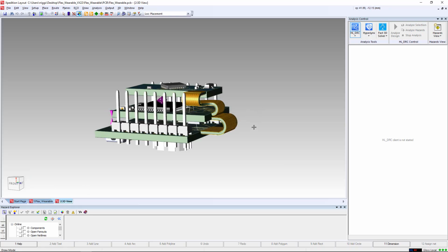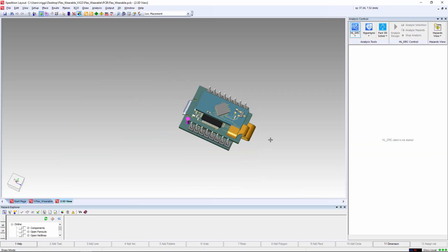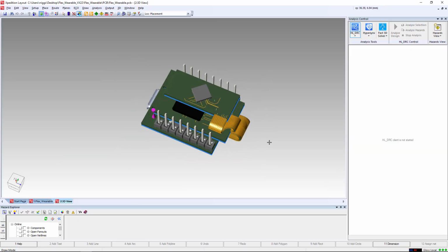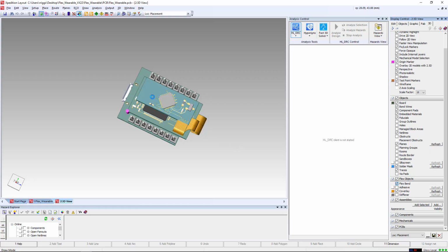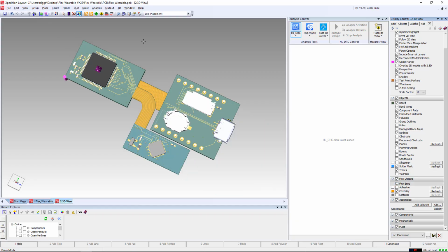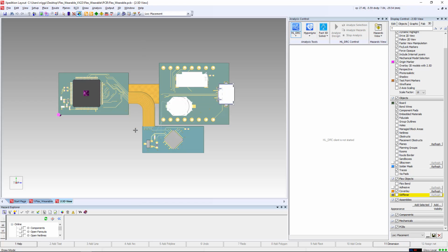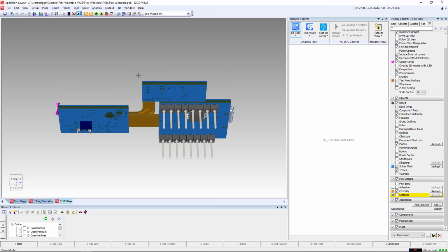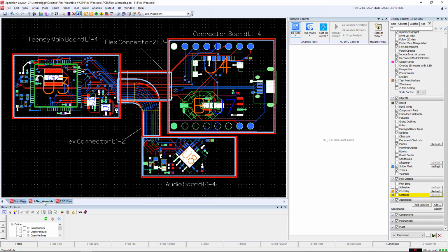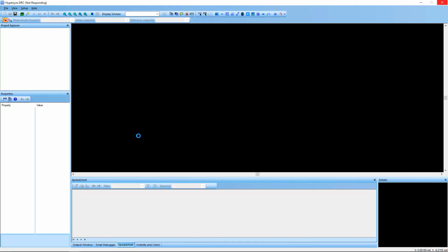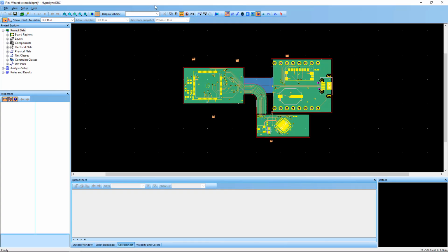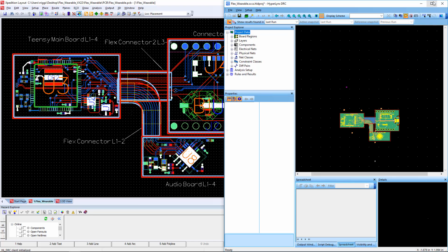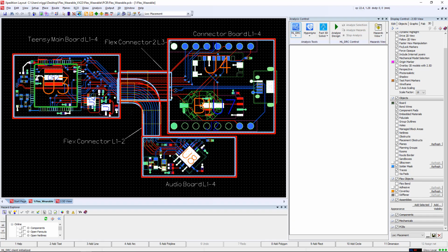So here we're looking at the same database in Expedition, and here you can see the 3D view of the database, where we actually can visualize with Expedition how our board will look in the real physical world with the flexible bends, and have the ability to manipulate that as well and do all our board database creation with Expedition layout. But for HyperLynx DRC, the rigid flex support is also available in streaming mode. So if you're using HyperLynx DRC inside of the Expedition flow and you're not using an individual standalone board, you can actually turn on the client there and activate streaming and then run all of your checks inside the Expedition environment as well. Now we're going to switch gears and talk about Wirebond support.